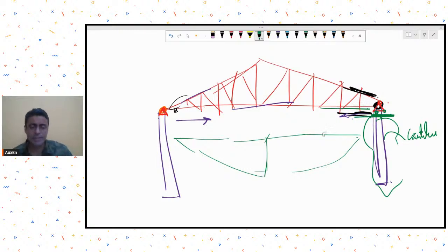You understand? There is no lateral support that you are getting between the truss roller joint and the column top. It is free to translate in this direction. Of course, it's not a pure roller. It has some slotted hole connection, so it can freely translate up to a certain point and then stop over there.